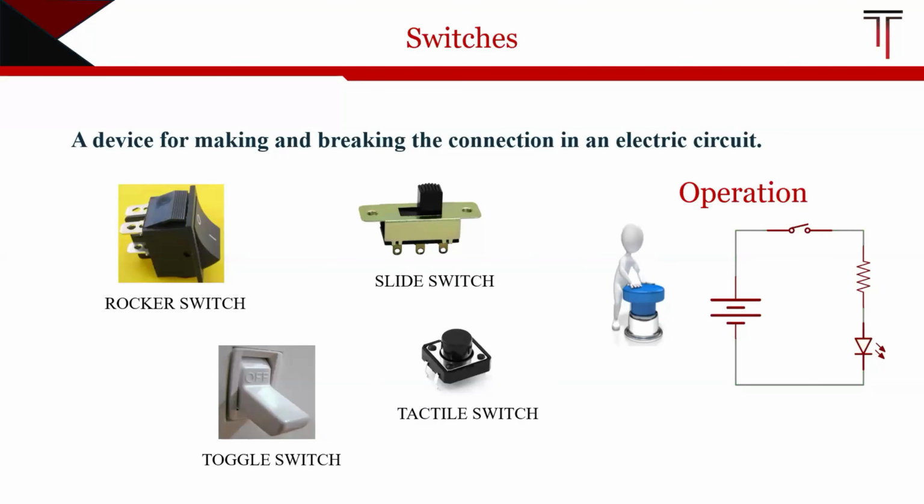These types of switches don't just close or open a circuit. They also play a role in defining the logical levels that get read by the microcontrollers. When the switch is open, no current flows, and the system might read this as low or high, depending upon the circuit configuration. When the switch is closed, the current flows and the system reads the opposite state.